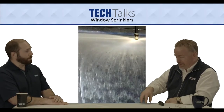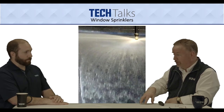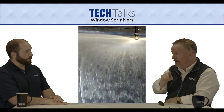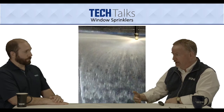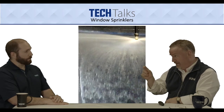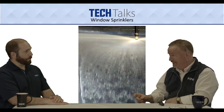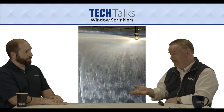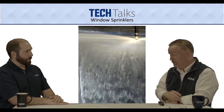Right. So in the testing, the heat source is right next to the window. We're blasting the window with the heat source, and then we're cooling it with this particular spray pattern by sheeting down, is what you're saying. So even if I have a small area that's not getting the sheeting of water, that could be a spot that causes failure in the whole window system, right?